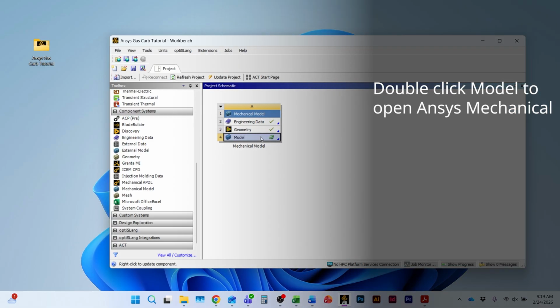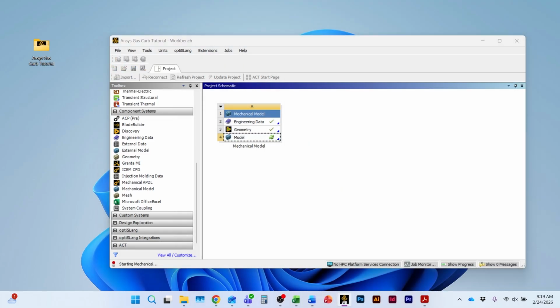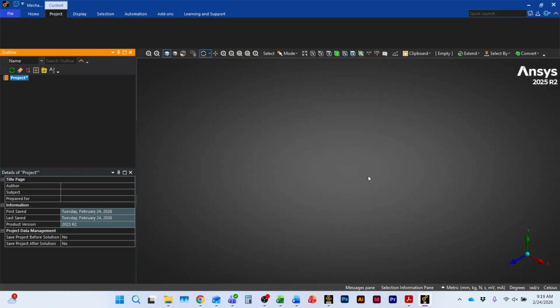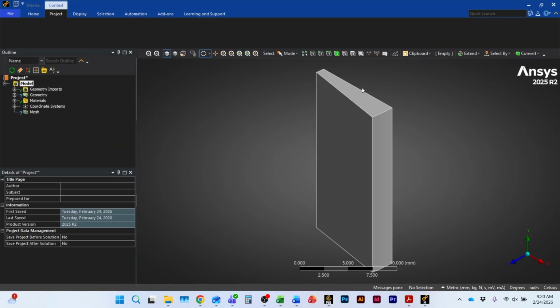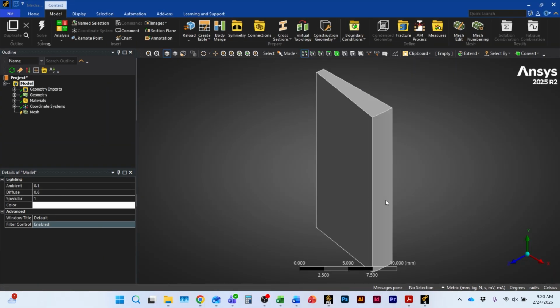Select Model. This is where we are going to be creating the mesh for this model. For the mesh, the general rule of thumb for a heat treatment model is to create a thin inflation layer on the exposed surface of the part so that we can accurately capture the carbon and temperature gradient for the different models we're going to build. This temperature and carbon gradient will have a significant impact on the phase transformations, stress, distortion, and other results for the model. If your elements are too coarse, you won't be able to accurately capture the behavior of the part in your model. Luckily, it's easy to adjust this mesh if it starts looking weird.